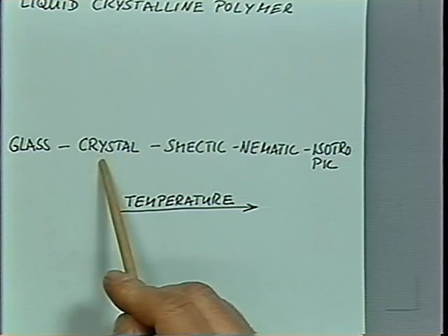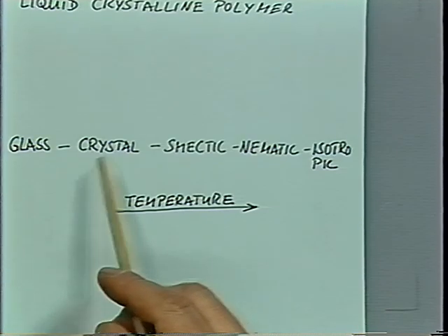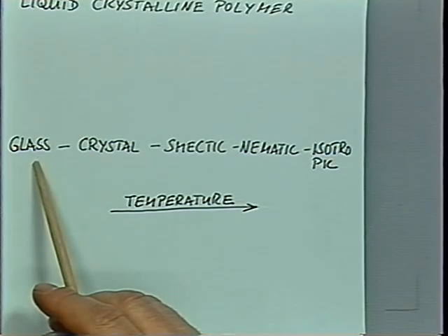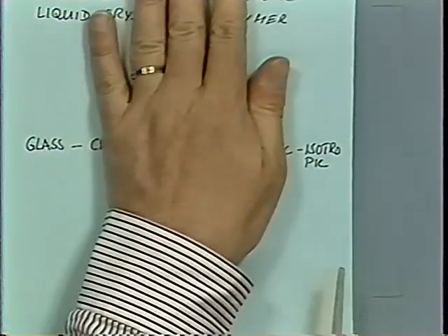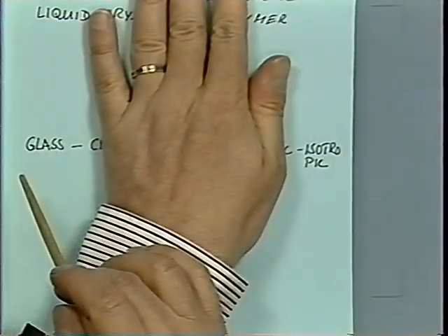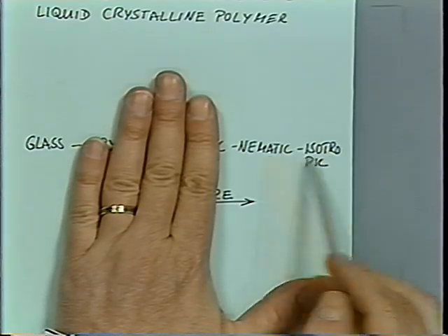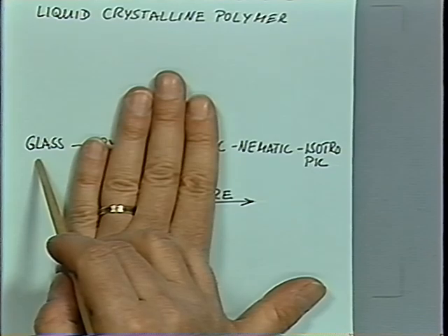And now we would have a solid, which is crystal, where the molecules are on a lattice, on an ordered pattern. And at even lower temperature, the part which hasn't crystallized yet will vitrify, so the molecular motion is reduced. There are systems which directly go from an isotropic state to the glass, like polystyrene, and there are systems which are liquid crystals which go from an isotropic to the nematic state and then to the glass. It would be nematic glasses.